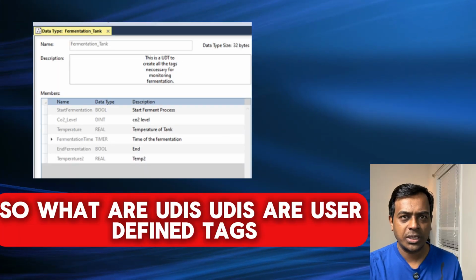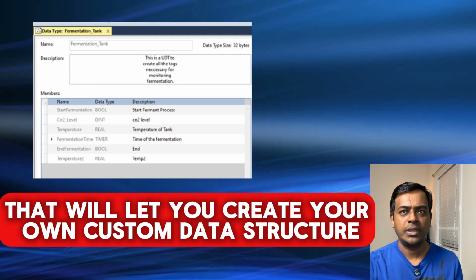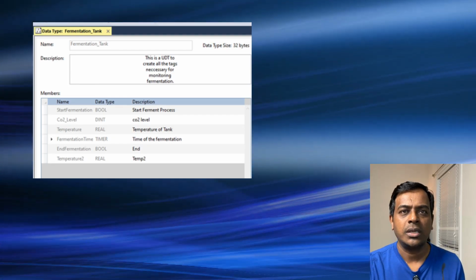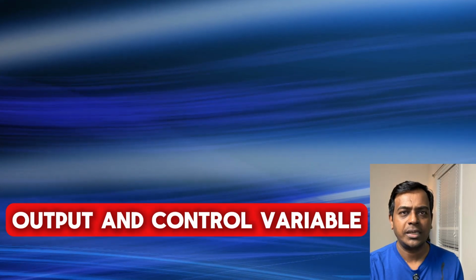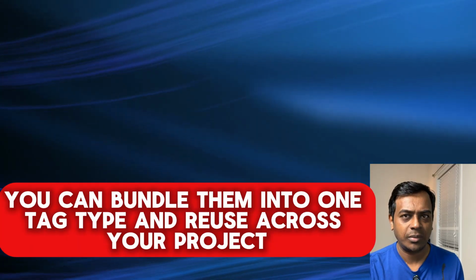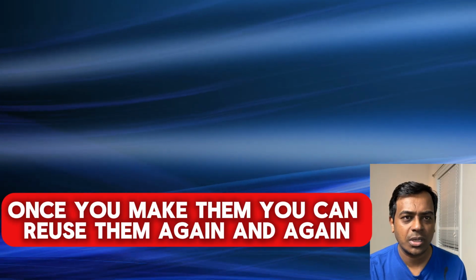So what are UDTs? UDTs are user-defined tags that will let you create your own custom data structure instead of making individual tags for every input, output, and control variable. You can bundle them into one tag type and reuse across your project. Once you make them, you can reuse them again and again.